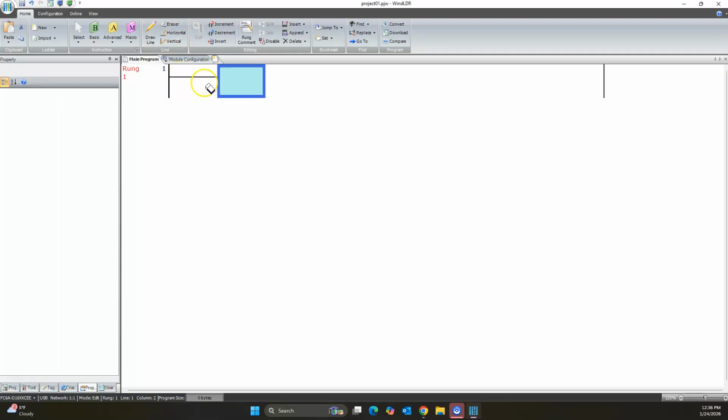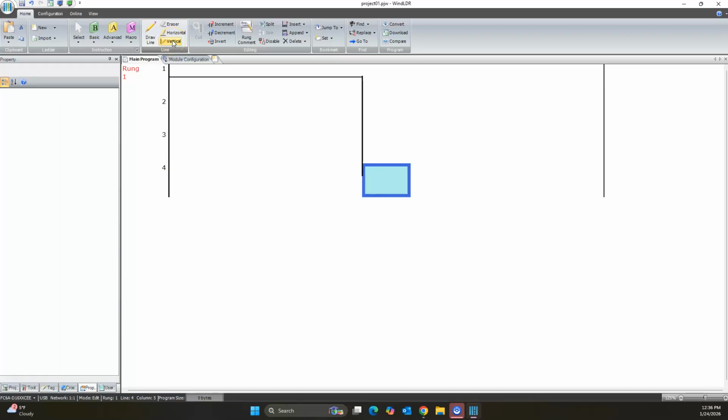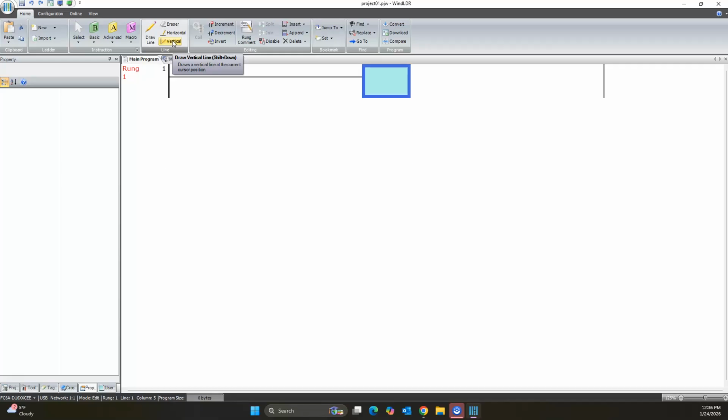And then we have making horizontal. If I click this horizontal, it just adds a horizontal line. Wherever this blue box is, it's going to populate a line in that column. This blue square represents one column on my overall rung. Then I can do the vertical, same thing. Now it's gone down one column vertically. Boom, boom, boom. Control Z, undo. That's your best friend in any software. Control Z, undo. That's the shortcut. That's what I'm doing right now. Control Z, Control Z, Control Z. Okay, cool.